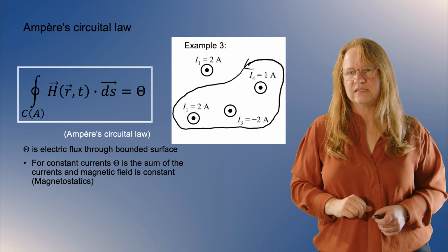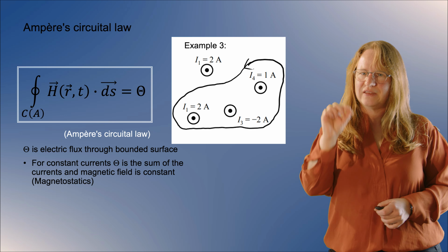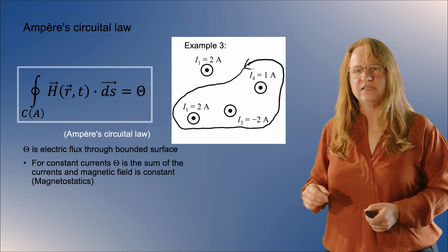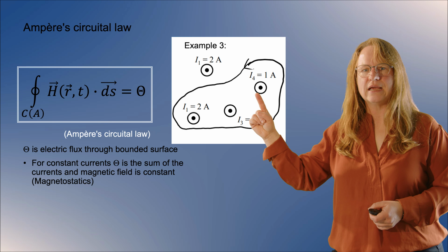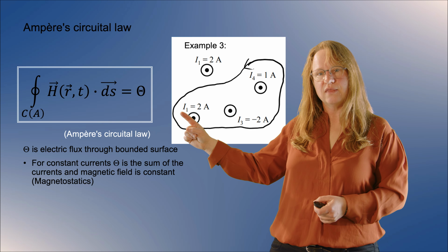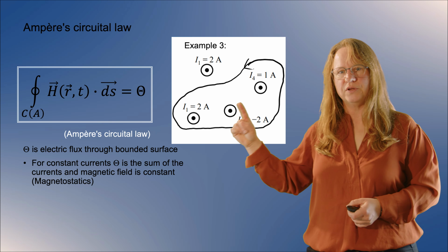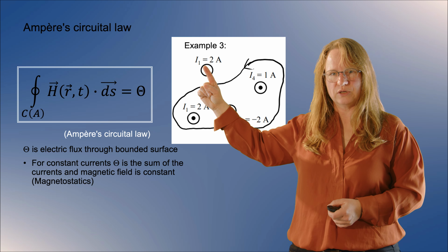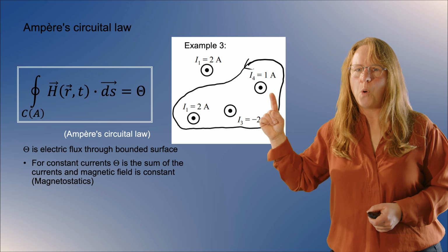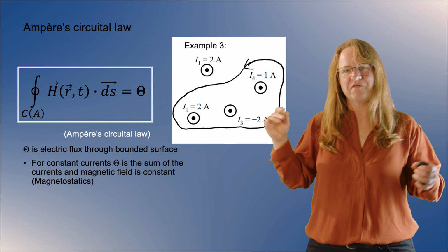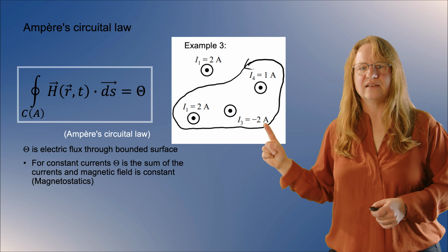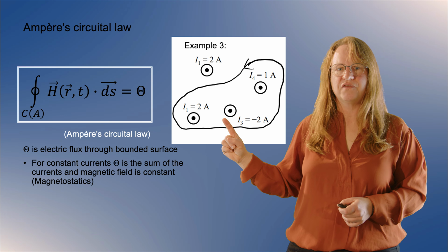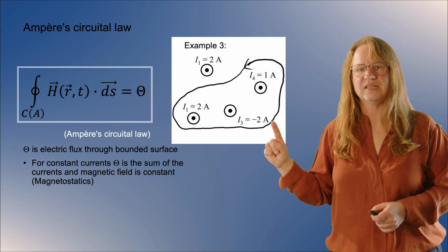So the currents that are positive, that have a dot tip showing, will count positive in. And here we now have 3 currents that are within the bounded surface, so they need to be considered. We have a 4th current that is outside, that does not need to be considered. And I have one more extra case here that is often happening, and that is that now we have a constant current I3 here that is pointing out of the plane, but it's negative.